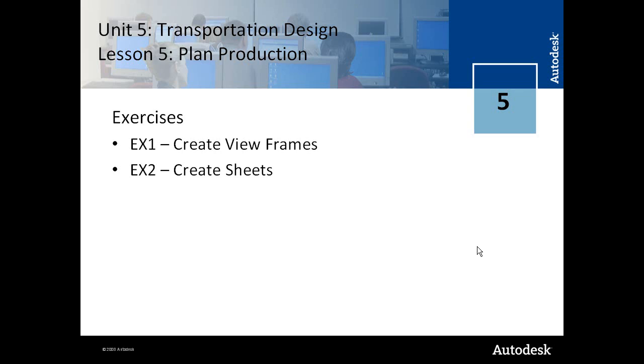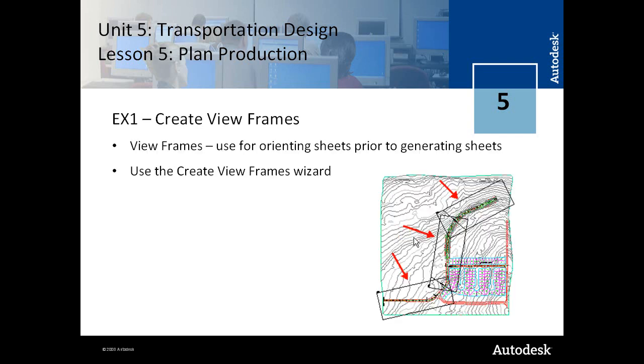The final lesson in the transportation design unit is on plan production, and in here you'll learn how to create view frames and to create sheets based on having an alignment and a profile view in the drawing. This is a powerful utility that allows you to automate the creation of plan profile sheets.